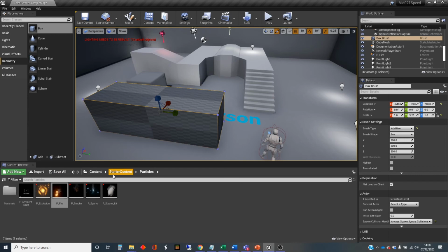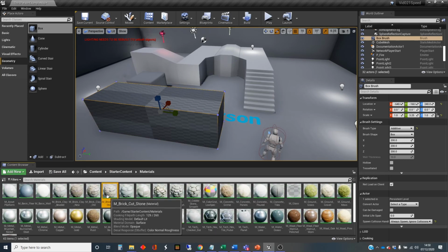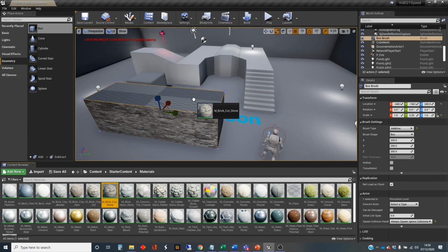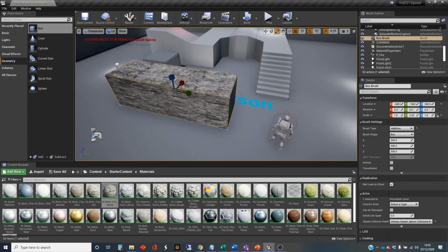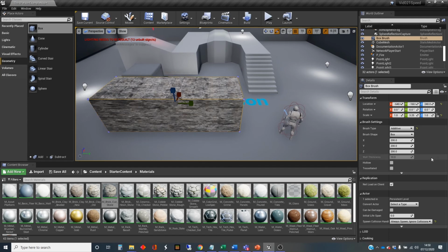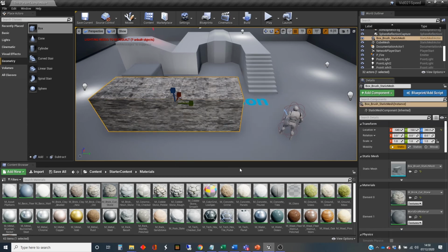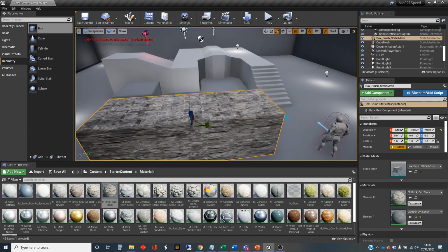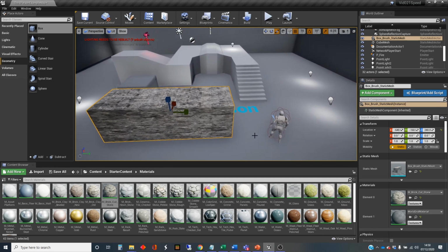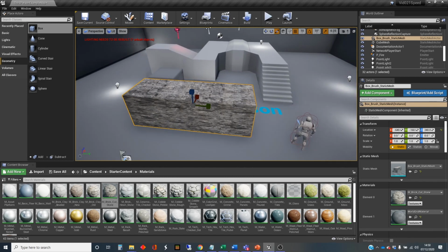So maybe we've done this, maybe we've had a stick of material on it. So I'll just quickly check materials on that. There it is on particular surfaces. And then inside this box brush, in the brush settings, go down here, click Create Static Mesh. It asks you where you want to put it, and then it's created that as a static mesh. If you do that to all your geometries, once you've got the shapes how you want them, then that can give you a huge speed up in terms of your level. So I've commonly seen this where I've had people doing a lot of geometry objects.